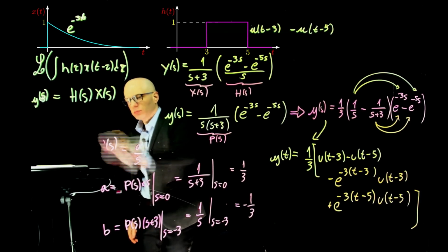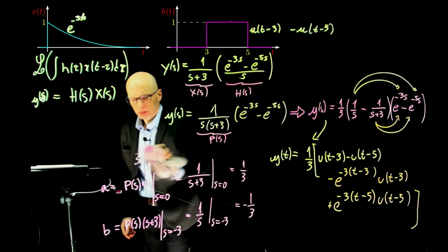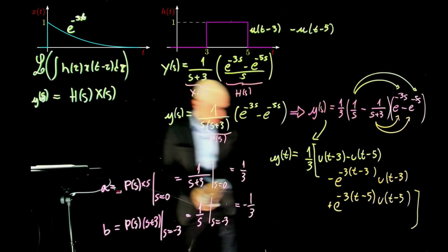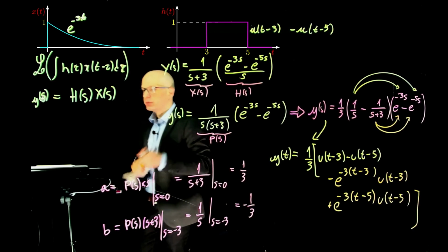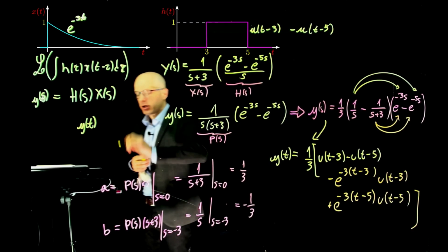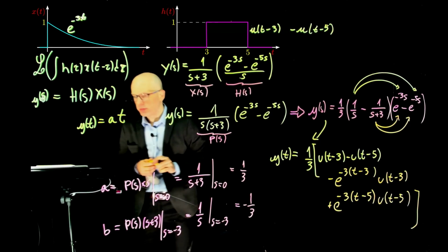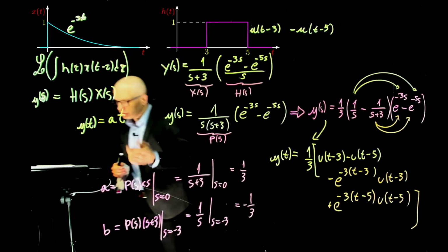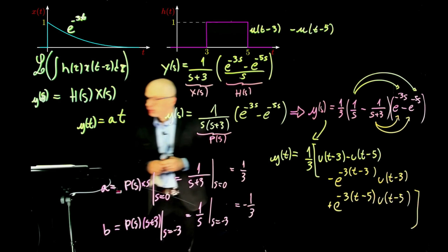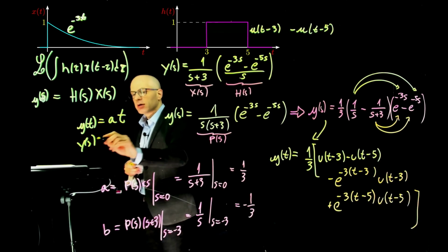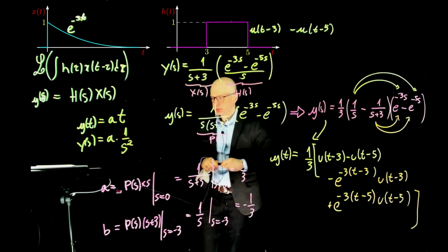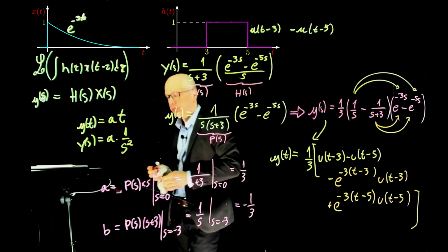Yeah, this isn't really related to this question, but what would the Laplace be of the ramp function? The Laplace of a ramp function. Yeah. So the ramp function increases linearly with time, so it would be something like y of t equals a constant times time. Now I can go to the Laplace transform. That would be in the table. There would be number 3, which gives Y of s as a times 1 over s squared. And that's the Laplace transform of the ramp.